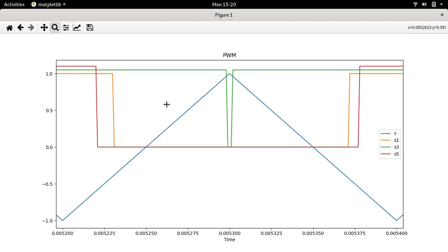So that's not changing. But then in that case, the ripple will be completely concentrated in this first half of the switching cycle. And after that, it will completely fall. This results in a kind of asymmetrical ripple, which is not very nice in an AC circuit, right? In an AC circuit, you would like something smooth and also symmetrical in both the positive and negative half cycles. That is also very important because remember, if you produce something which is asymmetrical between the positive half cycle and the negative half cycle, you may end up with a DC offset. You do not want to be injecting DC into an AC system.